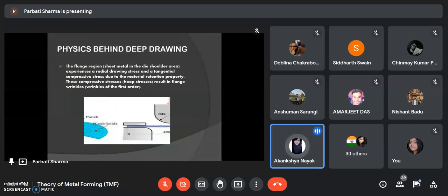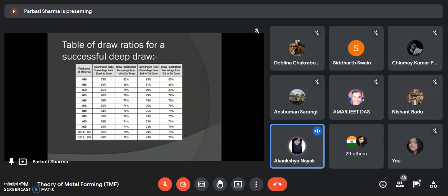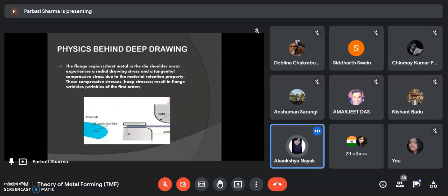So let me explain first in brief the mechanism of deformation. The deep drawing mechanism is a complicated process, particularly when it comes to the different types of stresses on each region in the blank. To facilitate the understanding of the mechanism, let's divide into three regions. The outer annular region is sandwiched between the die at its bottom part and the blank holder at its top part. The inner annular region is not in contact with either the punch or the die, and the central region of the blank is only in contact with the punch as illustrated in the figure.